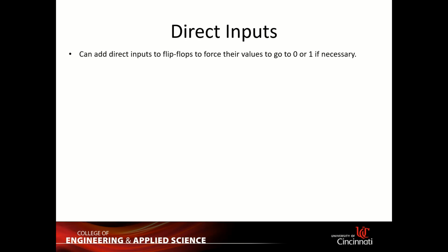Now we go to direct input. We talked about flip-flops. Actually the value of the output in a flip-flop very much depends on its previous state, right? So sometimes you need a way to directly assign a value into the output of the flip-flop, or maybe you need to reset it. It's good that you can hold the value, but sometimes you need to reset it, erase everything and start programming the flip-flop again. So this term is called direct input. Directly you want to force the flip-flop value to go to 0 or 1.